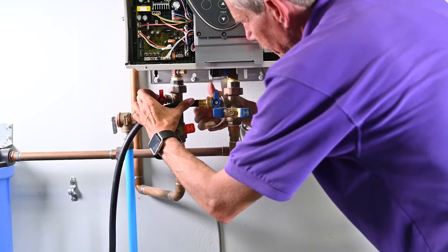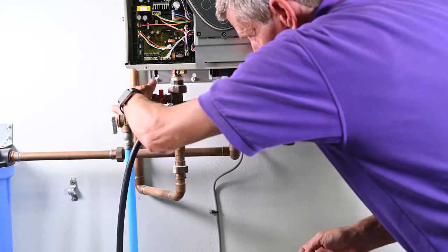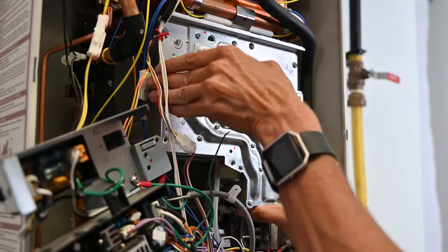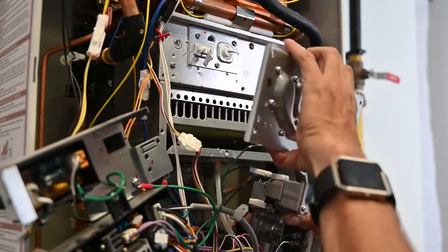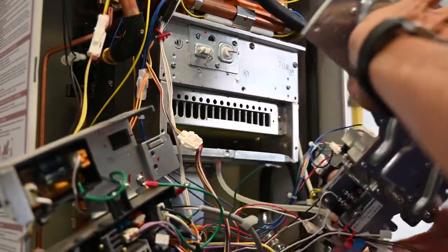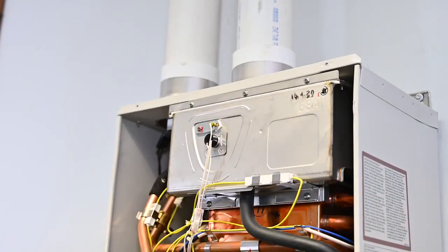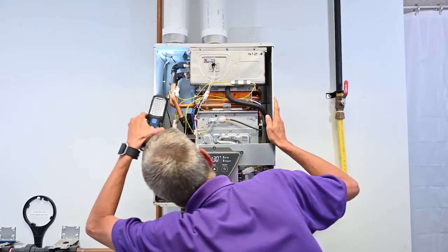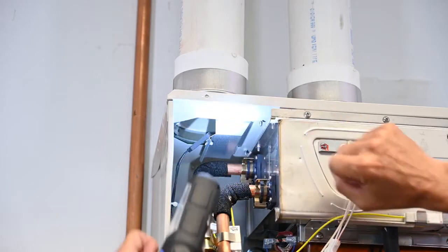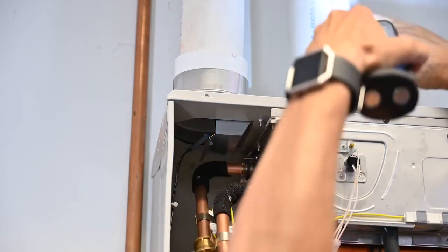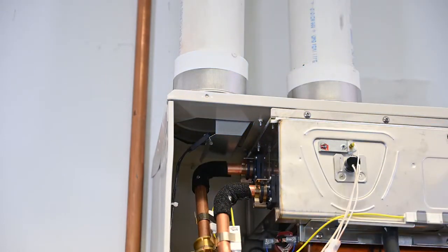Once properly installed, we highly recommend an annual maintenance schedule be set for the tankless water heater. Regular maintenance by a trained technician will ensure optimal performance and will extend the life of the tankless system. When performing maintenance on a tankless water heater, you should first check on all unit openings for proper combustion and ventilation airflow. Additionally, the entire venting system should be checked for any leaks, corrosion, blockages, or damage.